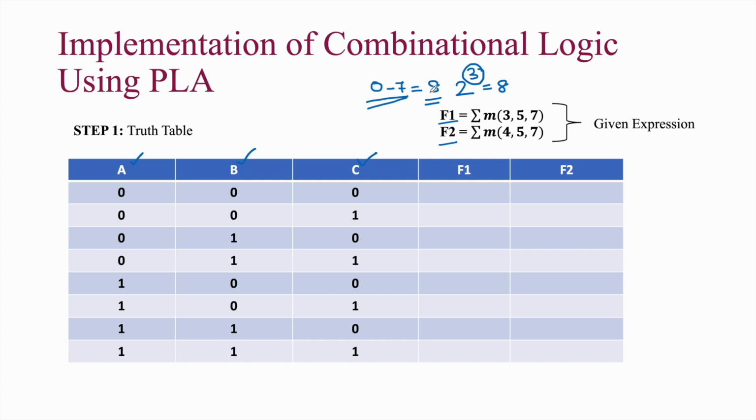So, right now if we are taking 3 bits, we will have 8 possibilities of minterms, starting from 000, 001, 010, 011, 100, 101, 110 and 111. So these are the 8 possible combinations for all these 3 bits of inputs. So it is done. Now, first step, we have to map this function along with these input variables.